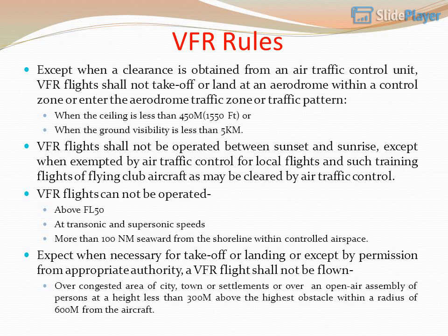VFR rules. Except when a clearance is obtained from an air traffic control unit, VFR flights shall not take off or land at an aerodrome within a control zone or enter the aerodrome traffic zone or traffic pattern when the ceiling is less than 450 m (1550 ft), or when the ground visibility is less than 5 km. VFR flights shall not be operated between sunset and sunrise, except when exempted by air traffic control for local flights and such training flights of flying club aircraft as may be cleared by air traffic control.